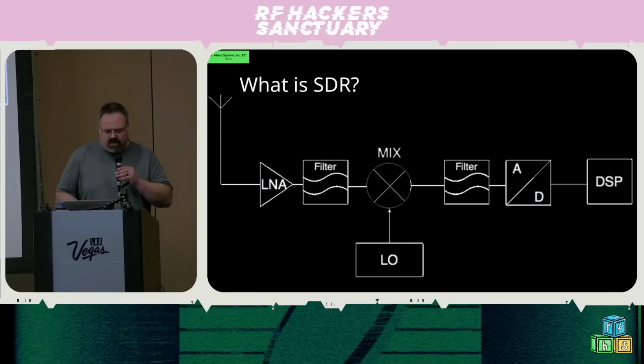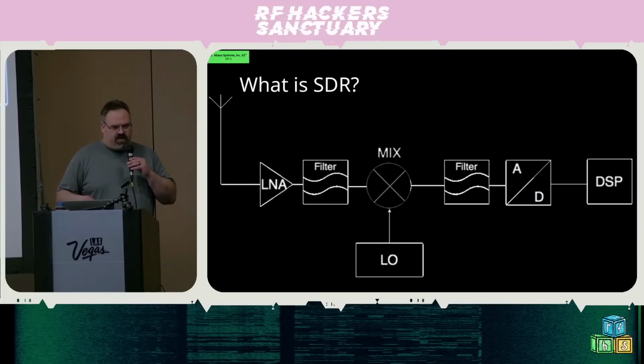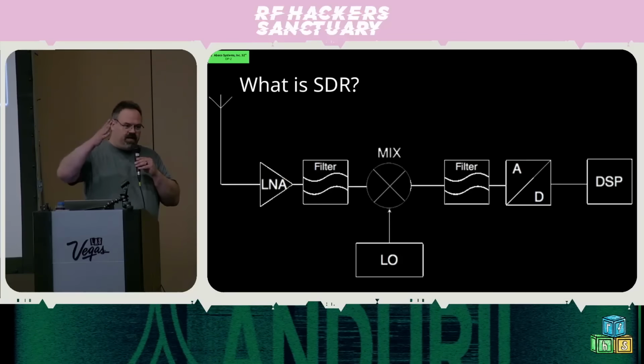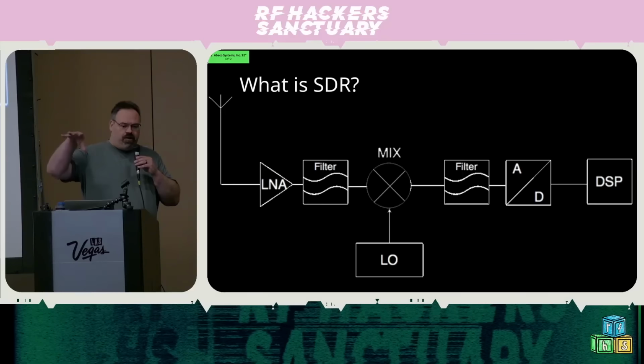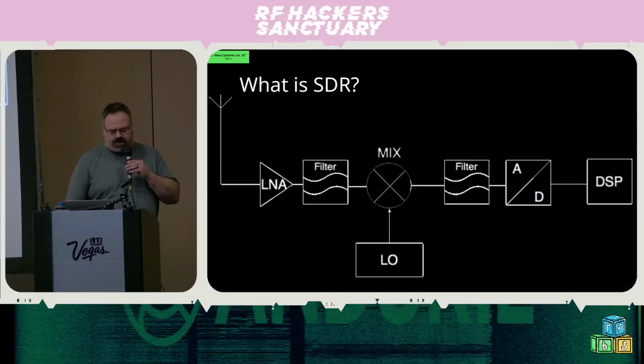Cool. So that's how you end up tuning your radio, is you use that local oscillator to feed in to the mixer to get the output that you want that will actually match up with your analog to digital converter.